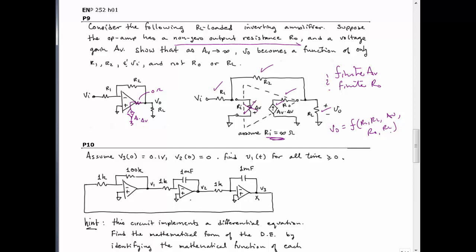And what we find here is that in fact if an op-amp really does have infinite gain, voltage gain, then it's not a limiting thing if the output resistance is not exactly 0, because the infinite gain can mask the fact that the output resistance is not quite 0. And that's what you're showing here.